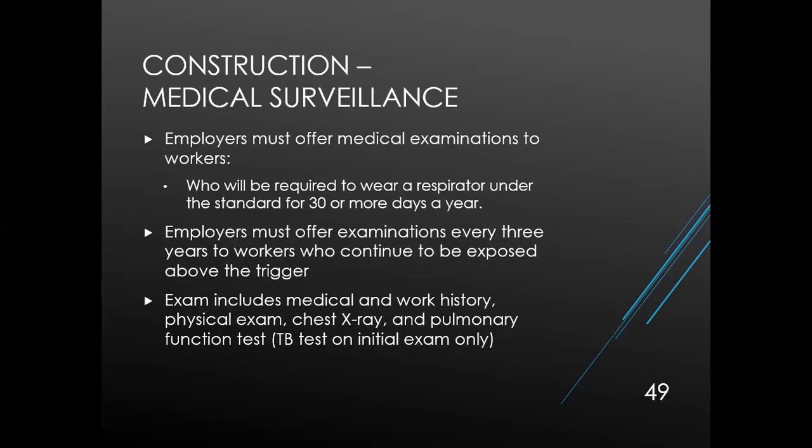The employer shall make medical surveillance available at no cost to the employee and at a reasonable time and place for each employee who will be required under this section to use a respirator for 30 or more days per year. These examinations must be offered at least every 3 years for exposed employees, and the exam shall include a medical and work history, physical exam, chest x-ray, and a pulmonary function test, and a TB test on the initial exam only.